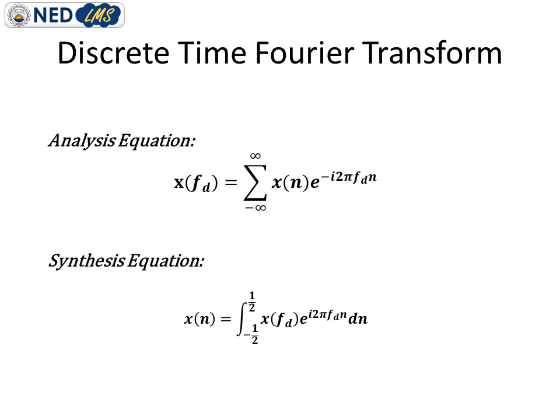So here in DTFT, the analysis equation has a summation sign for discrete time, and Fourier transform means aperiodic, which is represented by the infinite limit. From the synthesis equation, you will get a plot which is continuous in nature and periodic as well, indicated by the integral sign and the finite limit. So here you can comment that with the help of this technique, the discrete time Fourier transform, you can actually process your real world signal.